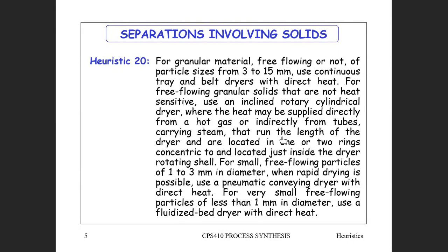So would we then rather use the continuous belt drying if something is sensitive to heat? I wouldn't. If possible, I would go with the fluidized bed.